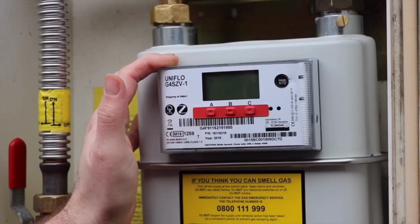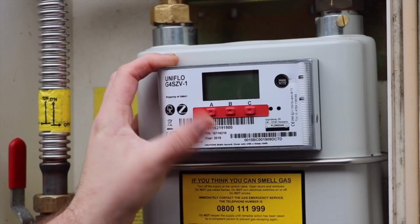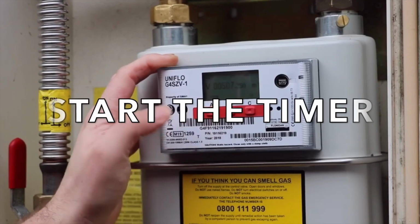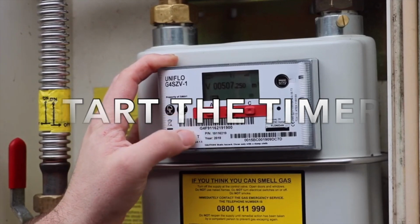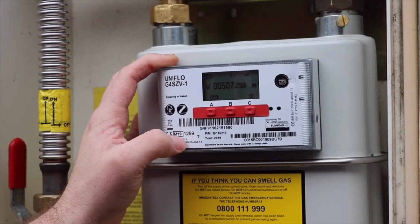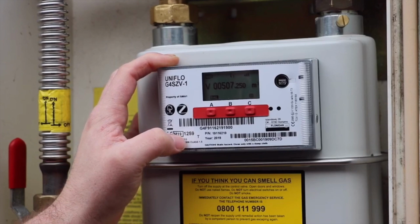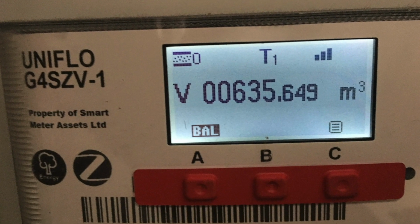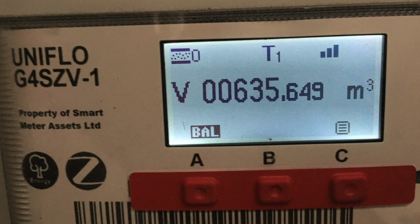So when you're gas rating with this meter, like you gas rate with any meter, make sure the appliance you're actually testing is running on full, and it's the only appliance that is running. Then you press any of the navigation buttons to wake up the display. The index is updated when one of the 3 buttons is pressed on the index plate. The meter will display this reading of the first screen and the index for up to 10 seconds.